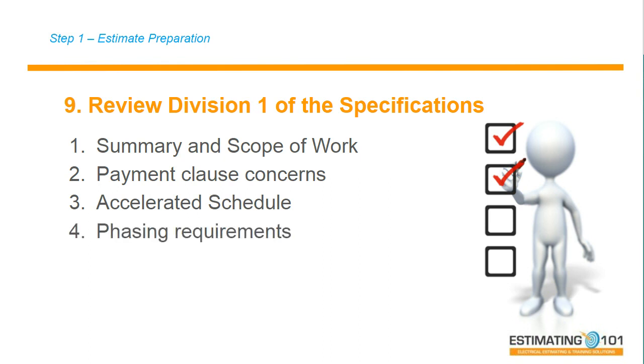When I say phasing, I mean the owner may want the first floor done in May, the second floor done in June, and the third floor done in August. So phasing is very important. If you're mobilizing, demobilizing, moving in and out of an area, you need to know that before you start counting and measuring anything on a project. You need to look at the work days and the work hours. I did a project one time in a hospital, and it said all work shall be performed between 12 a.m. midnight and 4 a.m. in the morning. They only gave us a 4-hour work window to do the work.